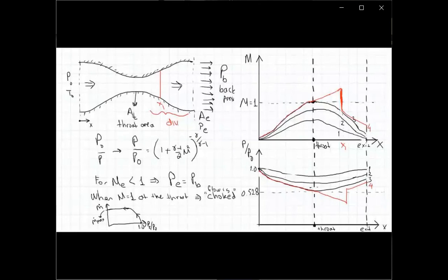Now, in this situation, we have achieved supersonic flow in some part of the nozzle. Here we have supersonic flow, but we don't have fully supersonic flow in the entire diverging part. There is still a shock wave. The supersonic flow, when it encounters this shock wave, will go to subsonic. So the exit will still be subsonic, and I haven't reached my objective.